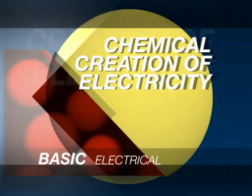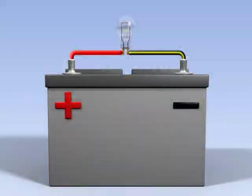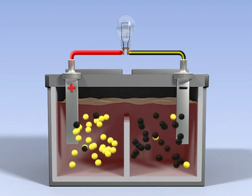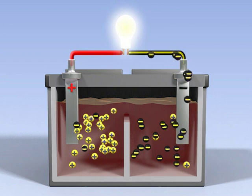A battery is an electrochemical device that converts chemical energy to electrical energy. The chemical that brings a battery to life is a solution of sulfuric acid and distilled water called electrolyte. A reaction between the electrolyte and the lead plates sets off a chemical change, an exchange of electrons, which in turn establishes a strong negative electrical charge in the battery. Since the rest of the battery has a lack of exchanged electrons, the battery therefore contains both negative and positive charges. During the discharge cycle, electrons are transferred from the electrolyte to the negative plates.